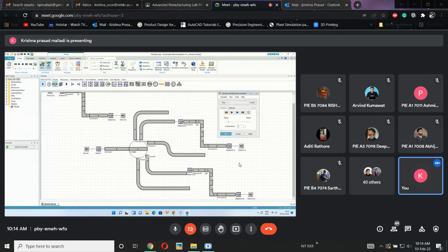Okay, so in Plant Simulation, one thing you need to understand: if there are 5, and you connect this conveyor with this conveyor 4, then it will be treated as the first connection. After that, if you connect these, this one with this one, this with this one, and then this with this one, that makes 5 connectors. If I connect like this, what is the first connection? Conveyor 4. Now if I run the simulation, see what will happen.